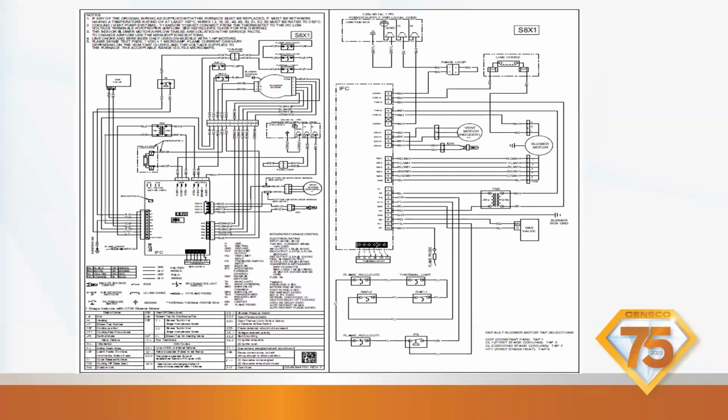It gives you a really simple sequence of operations way to follow it when you have both side by side. As you can see here on the pictorial, you have some plugs on the left, some on the top, some on the right, but over here on the ladder, they're all on the right. So you can then find this plug here over here and follow stuff through. Really helpful when they're side by side.